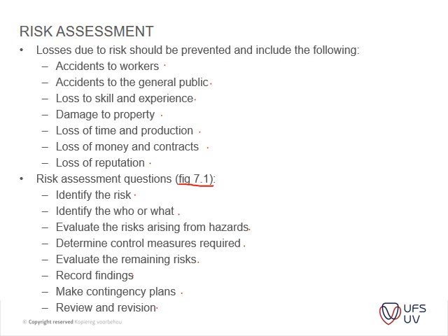Usually your health and safety consultants start with baseline risk assessment, and for each month they do an audit and they identify risks. But that doesn't mean that we as construction managers should not look at risks. For instance, some companies have ISO regulations which require you to look at your risks at least every 2 weeks, and not monthly, but that is dependent on each company.